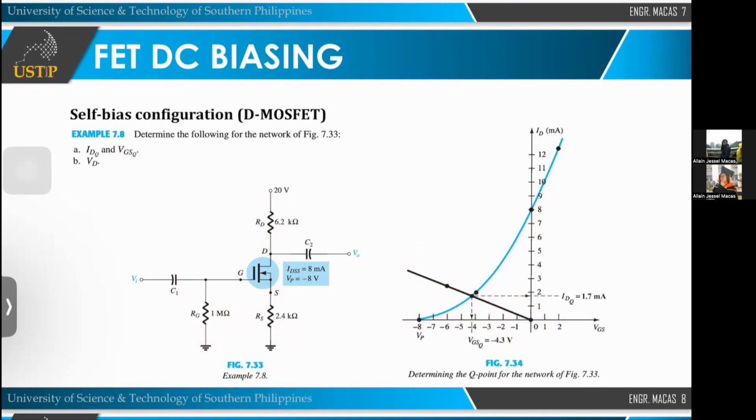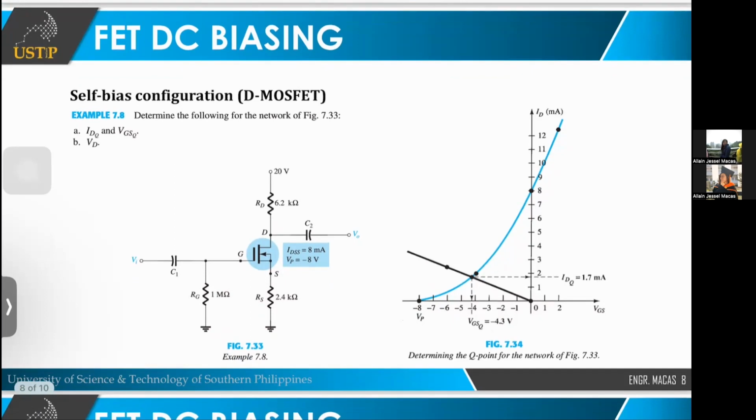So, that's why if you cannot solve it mathematically, you solve it graphically, though there may be some errors in your values because we are estimating. If you start to analyze or plot this curve, the transfer characteristic, we have to get the values of our ID given specific values of your VGS. So, we will plot three or four values.